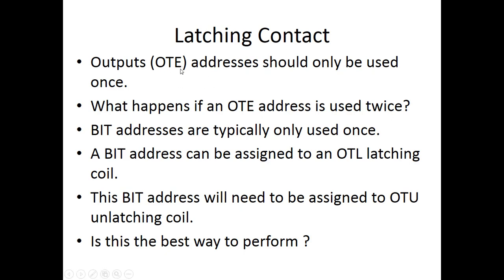We talked that an output should only be addressed and used once. Otherwise, you don't know if it's on or off. It'll scan, and sometimes it'll be on, and sometimes it'll be off. It can be very confusing, but typically the last time it's used will be the state of it. So don't use it more than once, or you're going to be confused.